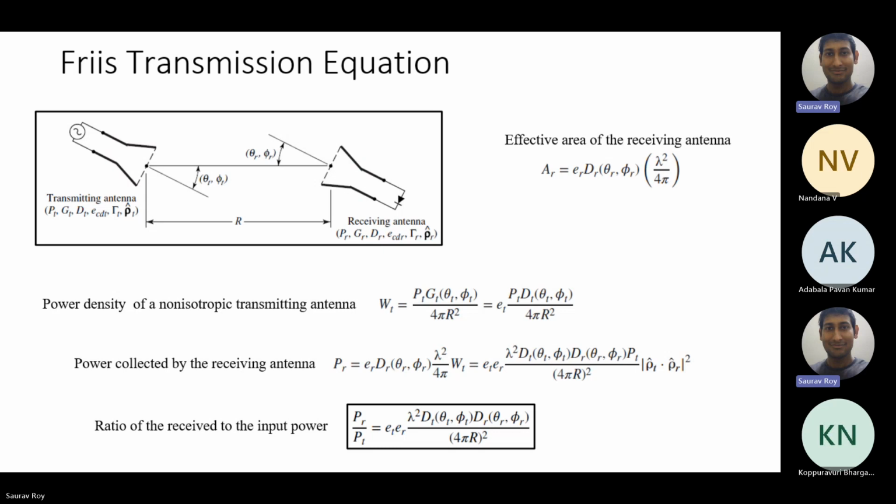Over that, obviously the link will be sufficient. So for that SNR calculation is done, and for the SNR calculation we see how much power is required, and for the power we see what kind of antenna can give you this kind of gain, or minimize the losses, so that you can do the power calculation. So from the received power, we'll calculate the SNR, and with that we'll check the bit error rate, whether it is meeting our specs or not. Based on that, we'll choose the transmitting antenna we wanted.